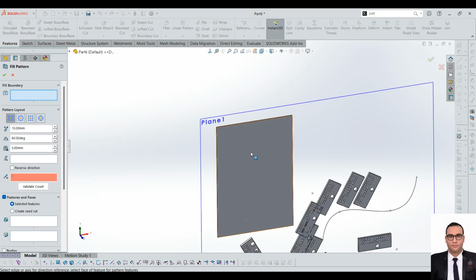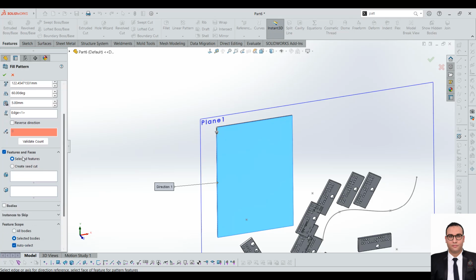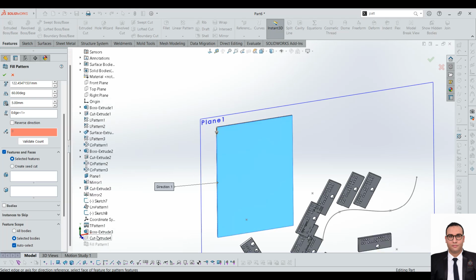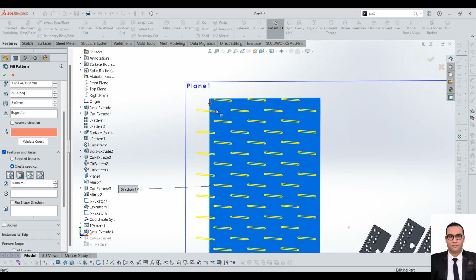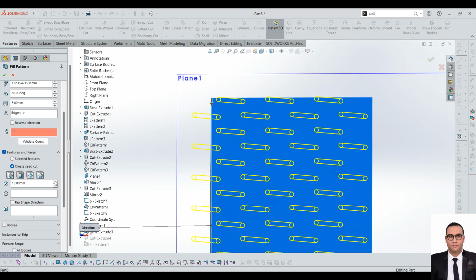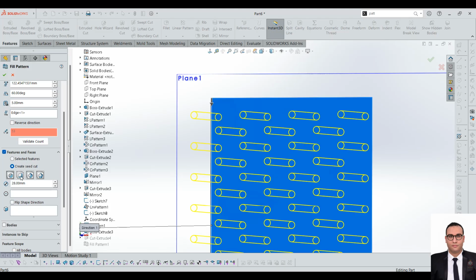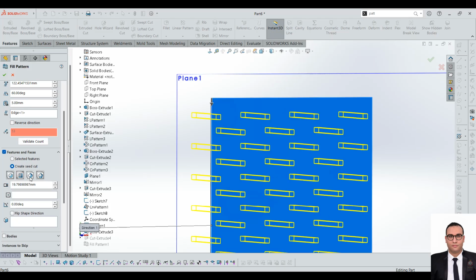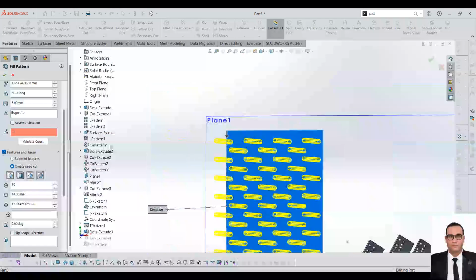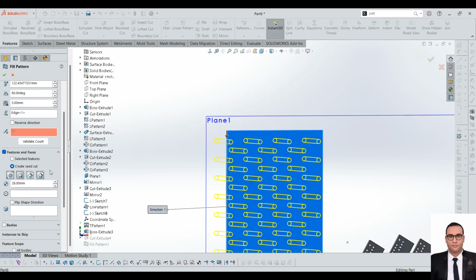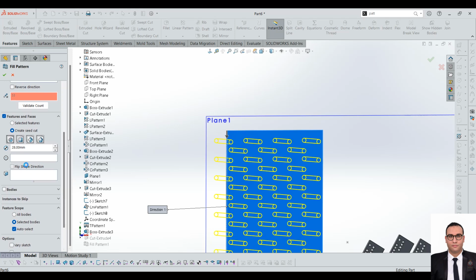We go to selecting this face, and then there is an option hidden here. See this feature that we selected earlier, this cut, or we can create a seed cut. See here, we can manipulate them as we want. We can make the holes bigger, or square shapes, or maybe a square with an angle, or polygon shapes. See here, and we can select them rapidly if we want to fill that out without any problem. And there are a lot of options.